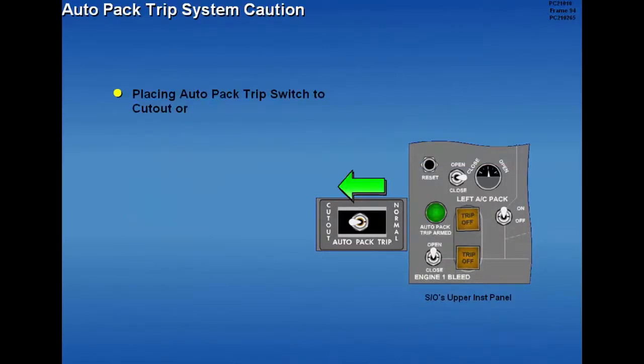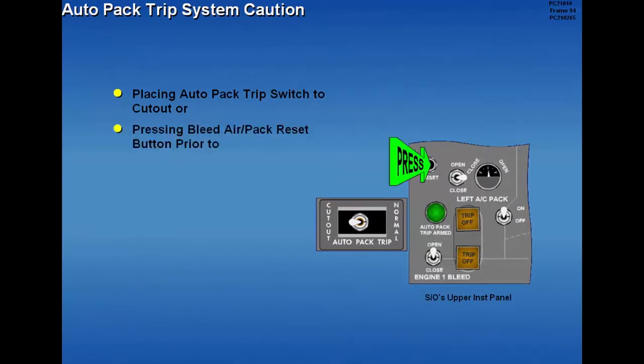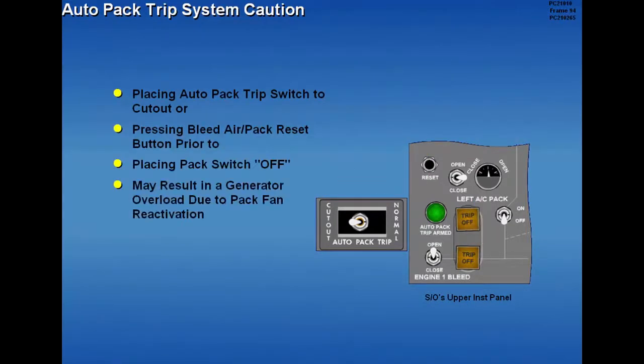Placing the auto pack trip switch to cutout or pressing the bleed air pack reset button prior to placing the pack switches off may result in a generator overload due to pack fan reactivation.